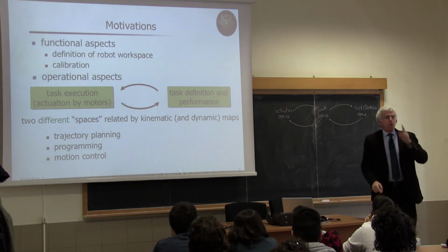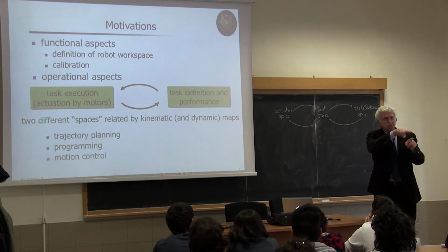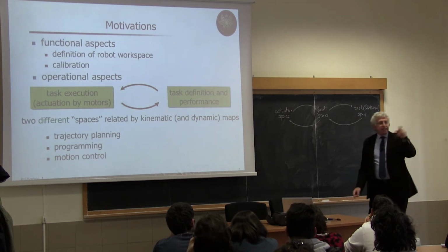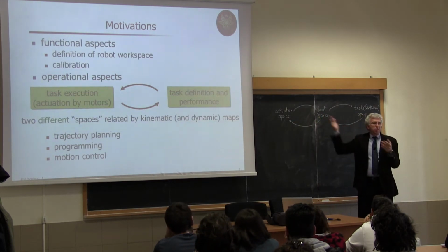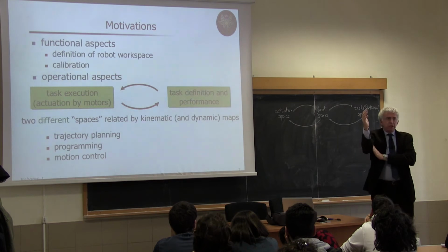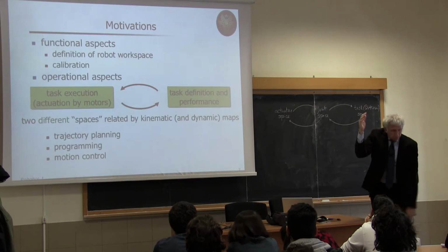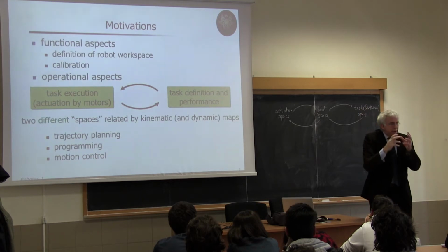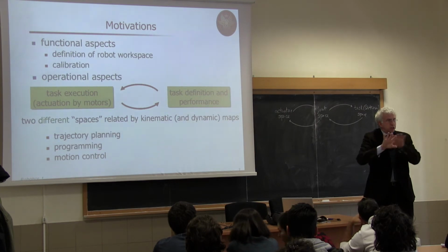Now, if you have one motor per joint placed exactly at the joint, let's say a DC motor doing some rotation, then scaled by a transmission ratio, but then moving exactly that joint, so the actuator space and the joint space can be merged together. It's just a scaling factor, maybe. But you may have different situations where two joints, for instance, my shoulder and my elbow, are moved by two motors which are on the base of the structure. And they cooperate together. Both motors are moving both joints, not separately.